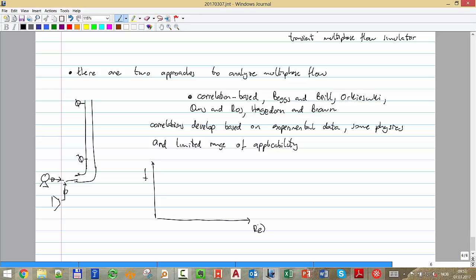They found that the Reynolds number, which is some velocity scaled, the relationship between inertial and viscous forces, v rho divided by mu, but it's kind of an adimensional velocity, gives you a very nice correlation with the friction, with the pressure drop.